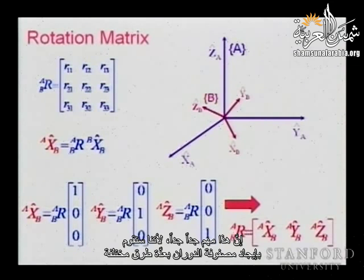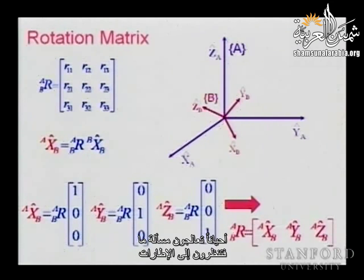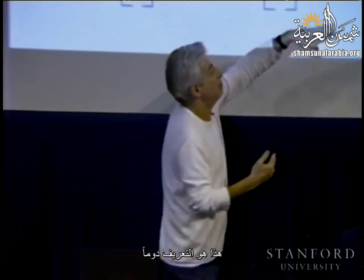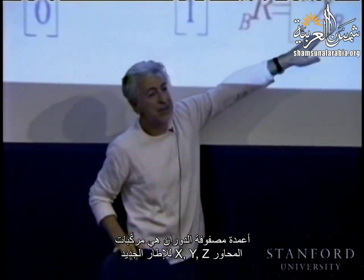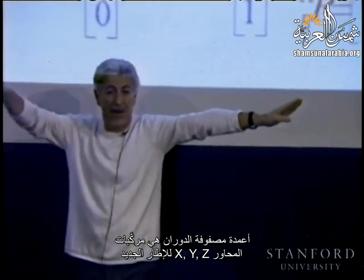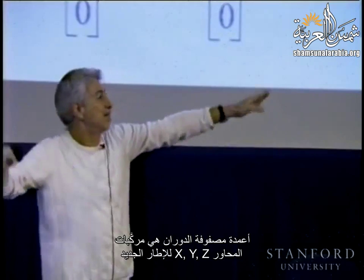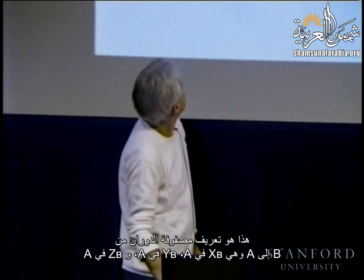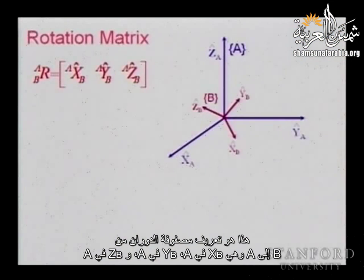This is very, very important because we are going to find the rotation matrix through many different ways. But sometimes you are looking at a problem and you are looking at the frames. Look at the components of that frame in the other frame, and you will make sense of your result. This is always the definition. The columns of the rotation matrix are the components of the axes x, y, z of the new frame in the reference frame. Okay? All right.